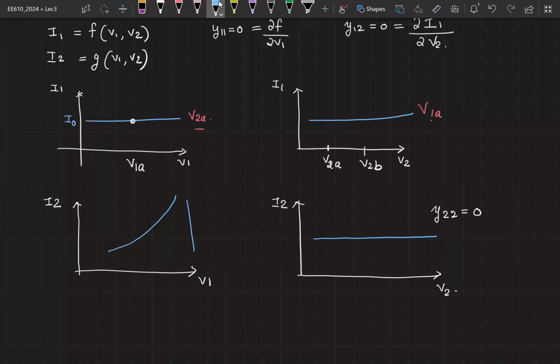If the gain is infinite, then it means that the output is independent of the input, right? We want the gain to be as large as possible. Ideally, it should be straight. We take gain as infinite, ideally it should be straight. We'll come back to this gain equal to infinity part in a little while. The reason is if gain is infinity, it can also mean that you get an output even without an input. We want the output to be some scaled version of the input. So you need the slope to be very, very large, the limit of which is infinity with a straight line, but infinity is a slightly tricky point. So we'll just say that we want the gain to be very large.